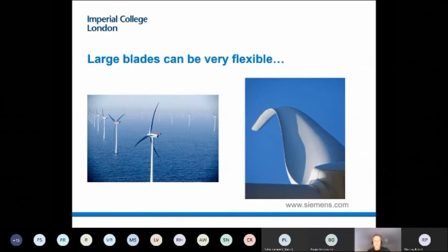The second is you would expect that things scale linearly. So you have a larger wind turbine, therefore you have the same amount of flexibility just over a larger area. The actual truth is no. If you scale the weight of wind turbines with the power, that doesn't go linearly. So as wind turbines become larger, things don't scale as nicely. And that means you need to start putting constraints somewhere else. One of them is reducing the weight of mass on the blades. So it's not something you like to see, but it's something you have to deal with and live with.